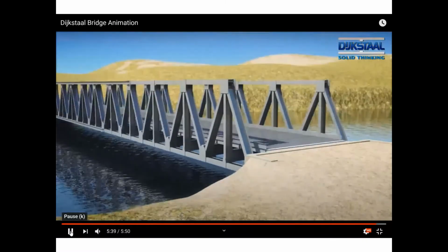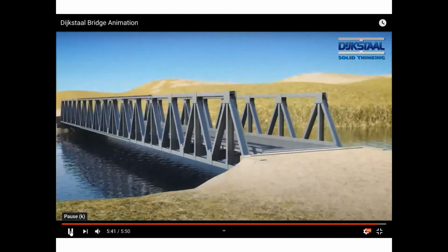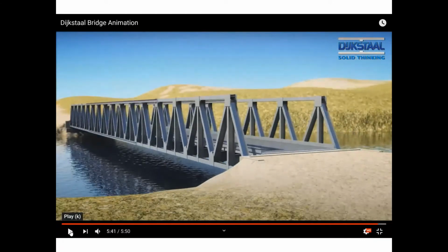So guys, truss means members connected together. Most of the time they are steel members connected together by something called a joint. In real life, these joints look like plates and bolts connecting these members together. Then the whole structure is supported from one side on a support and on the other side on another support. Your support is probably a hinge, roller, or sometimes fixed.